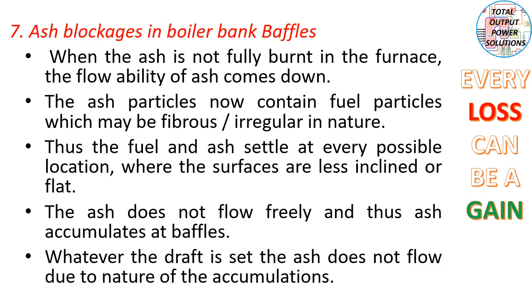Then ash blockages in the boiler bank baffles. When the ash is not fully burnt in the furnace, the flowability of ash comes down. The ash particles now contain fuel particles which may be fibrous or irregular in nature. Thus, the fuel and ash settle at every possible location where the surfaces are less inclined or flat. The ash does not flow freely and thus accumulates at baffles. Whatever the draft is set, the ash does not flow due to the nature of the accumulations.